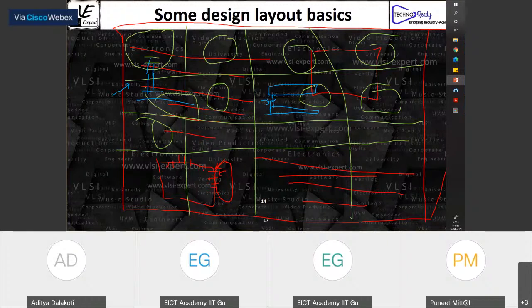In the open source tools, for visualizing congestion, I'll show you. It actually puts it in the script. In the log files, you can see that it tells you the routing layer congestion available to you. It is not able to do it with respect to pins and cells. It does give you a routing layer congestion report. I can show you it in the log file in just a bit. We'll go to the config file in a bit. Naveen, yes, I'll have a little bit of explanation here. I want to go into what those different configuration file settings do.